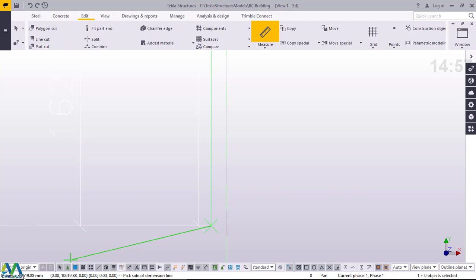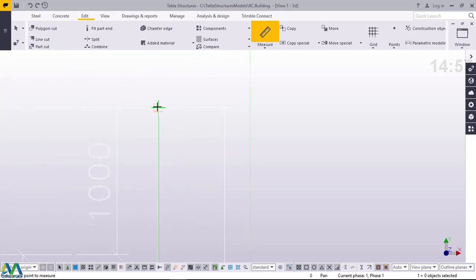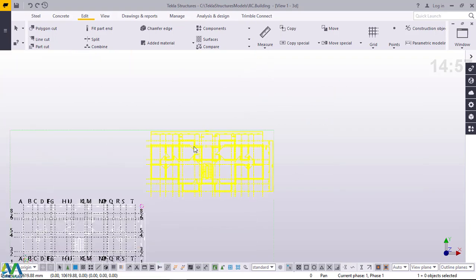It's 10.6. Let me just redo it. Let me snap right there just to make it much more accurate, then run all the way to that end and snap right there. It is actually 10.620 if you round that off. Now this is the scale we wanted.